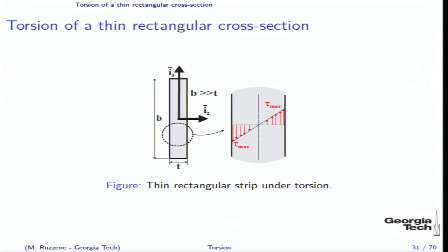So that's your maximum stress which you can evaluate, and then based on that you can design your thin walled section. If you're given a particular allowable shear stress, you can use that expression to evaluate the shear stress coming in the section, and then you can make a decision whether that beam is good enough for your problem. And then we will solve for warping.